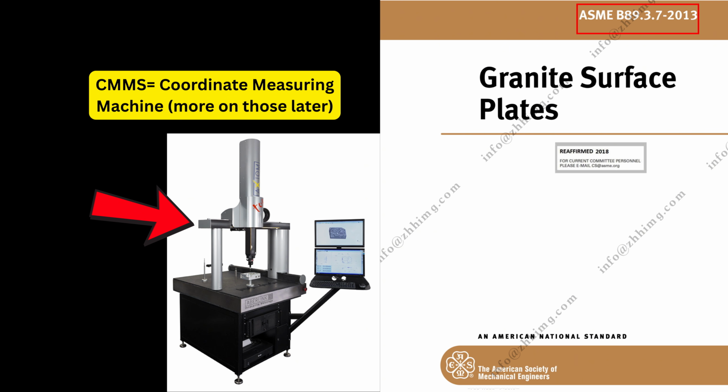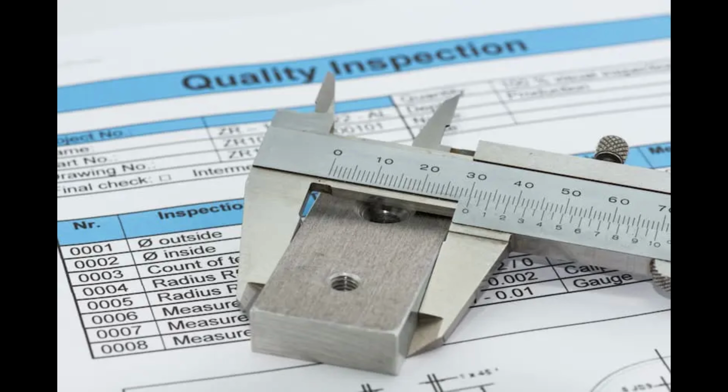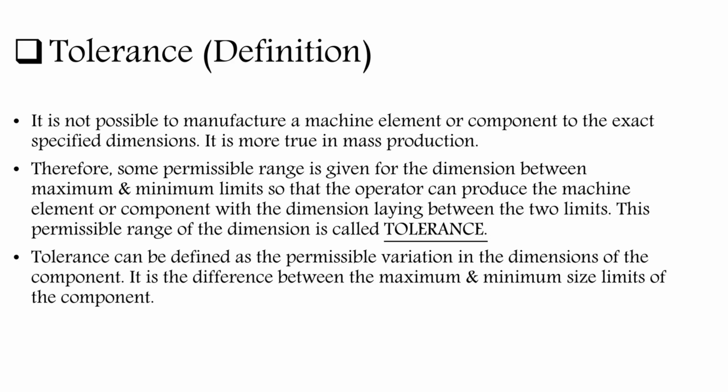I am going to break these standards down into categories with the criteria: what measurement tool is needed to appreciate and measure the flatness, and what method today can achieve that tolerance. In engineering, tolerance is the permissible variation in the size, shape, or position of a manufactured part from its ideal, nominal, design value. In other words, how big or too small are you willing to tolerate before the part becomes unusable? Tolerance is measured as a plus or minus by a certain value off that nominal designed value.